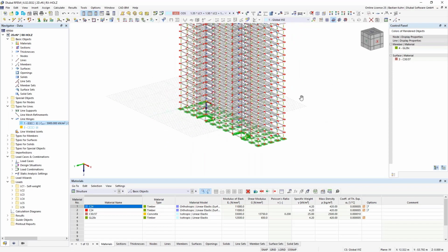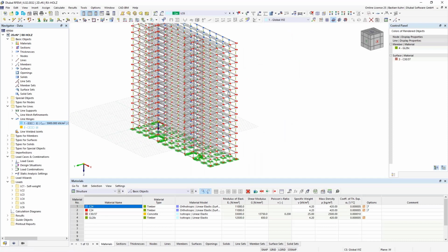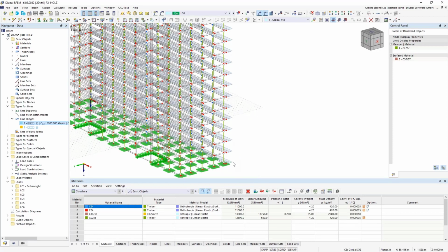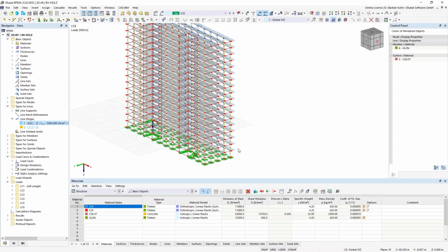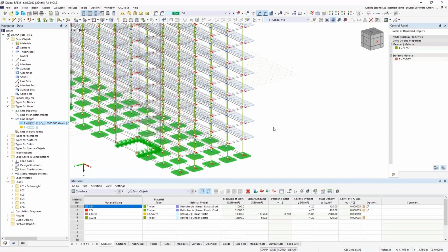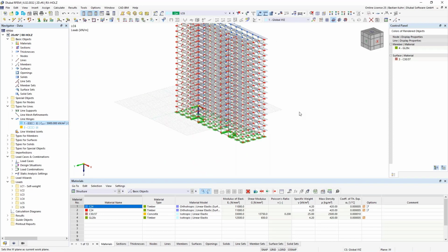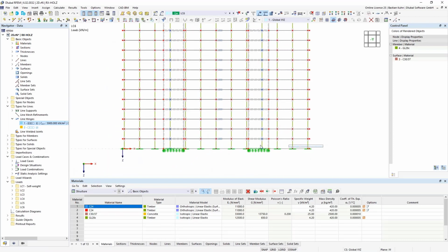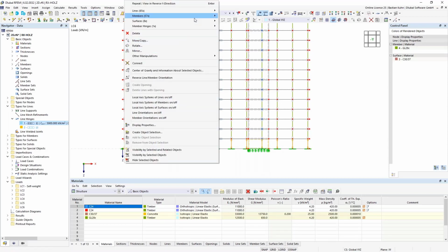Now there is a problem with the load K6 because a line load needs a surface to which it is attached. Otherwise it will not work. Therefore I'm deleting the one load on the bottom. Usually the wind load needs to look different. It needs to be higher on the top story than on the bottom areas. And I should have implemented here also a force that's attaching to the columns, but I think it's okay for this webinar.